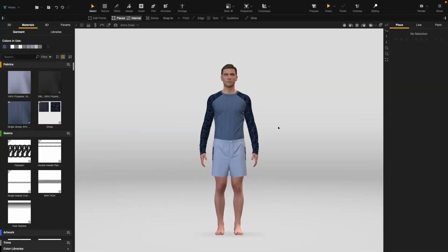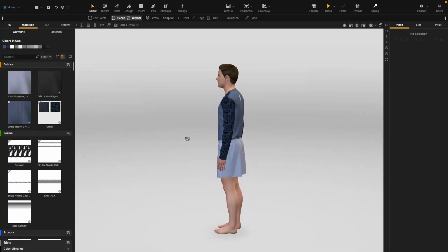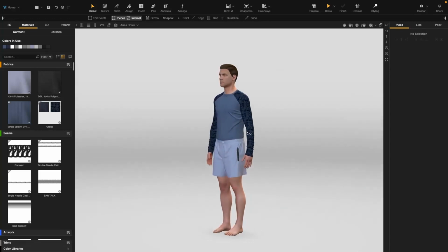Now let's learn how to navigate with the Maya navigation mode. We need to press on the Alt key when navigating in the 3D window. For Mac users, this is the Option key. To rotate in the 3D window, we press and hold the Alt key and use the left mouse button. Next, we drag the cursor to change the viewpoint as required.